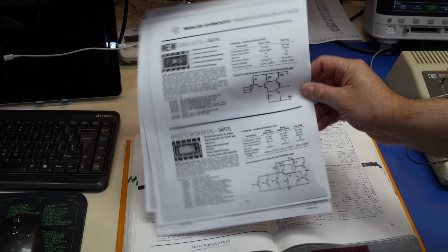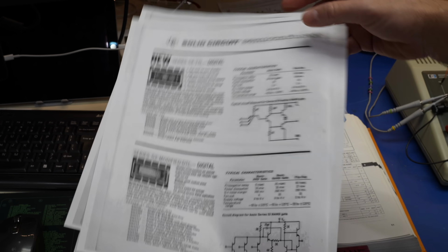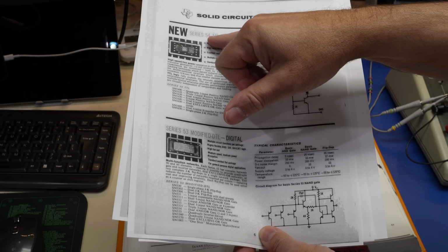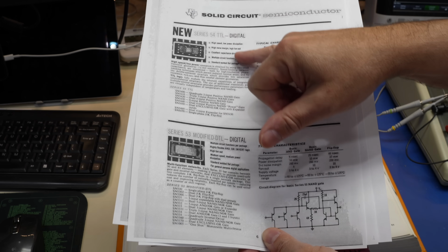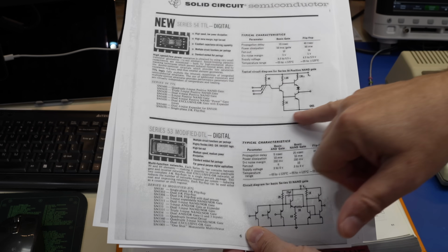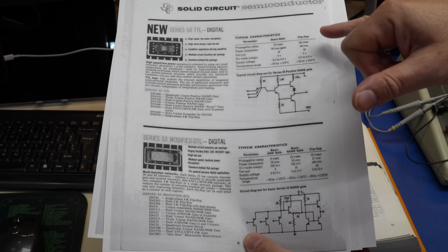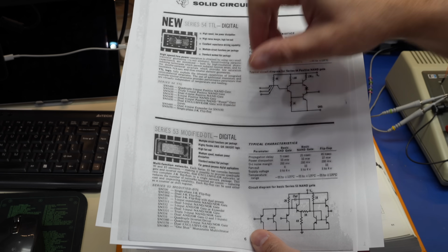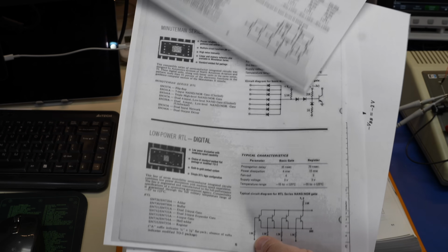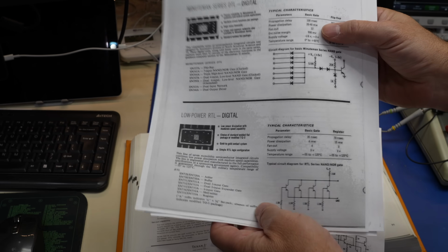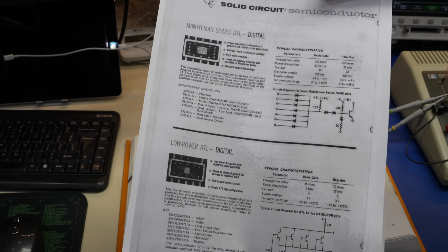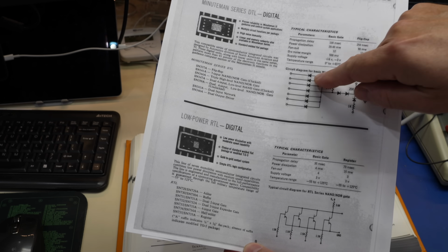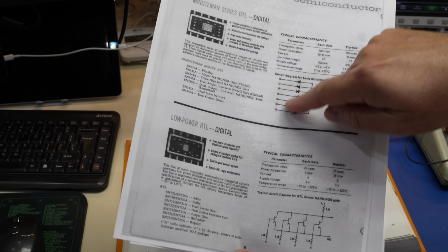Here you go. So that's a copy of the 1965 catalog. New series 5400. So it started with the military series, and here's our TTL gate, and it's the same schematic as I just showed you. TTL stands for transistor-transistor logic. Why that? Well, if you look at the other page, you can see what other series they had before. They had DTL, diode transistor logic, where you have a bunch of diodes doing the ANDing or ORing function.